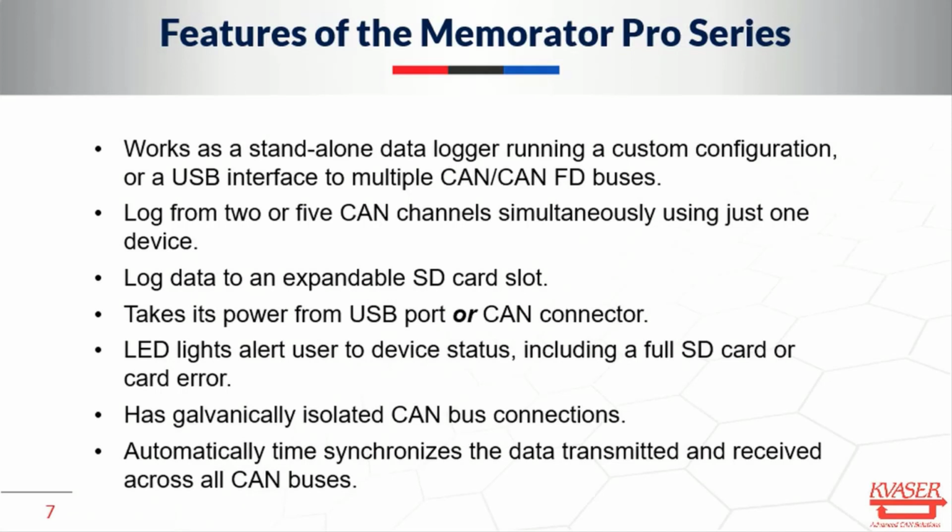They log from either 2 or 5 CAN channels simultaneously, using just 1 device, of course. They log data to an expandable SD card slot. I say expandable because that particular SD card slot has been tested all the way up to as big an SD card as is provided these days, I think a 512 gig. They take their power from the USB port or from the CAN connector.